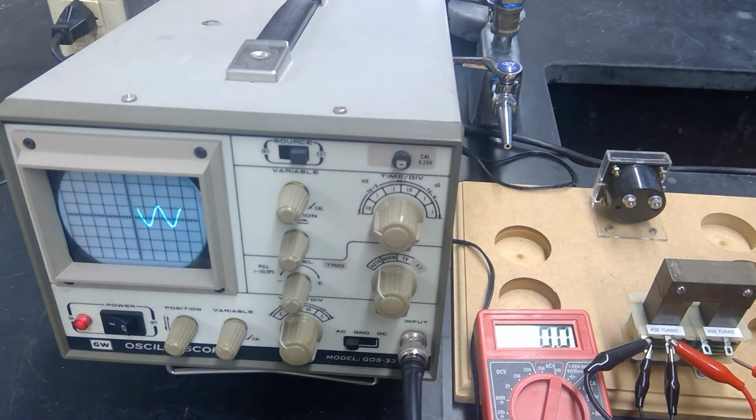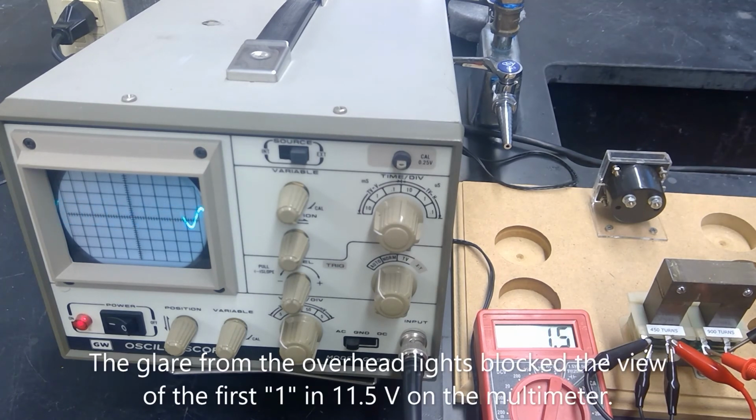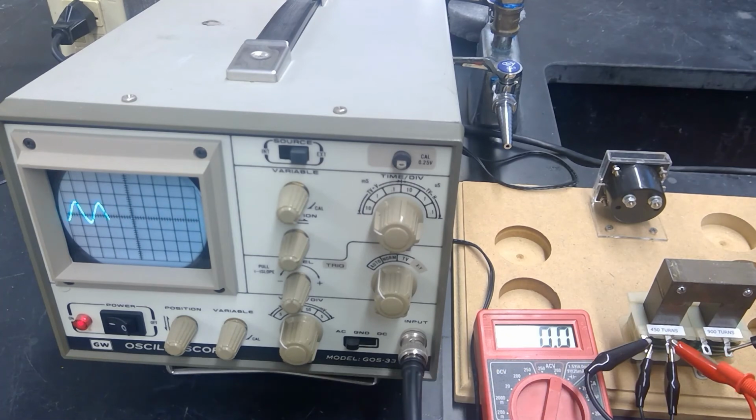But now let's take a look at the secondary. And sure enough, it's a lot bigger power. As a matter of fact, in theory, if we had a perfect transformation, because this is the double number of turns, we should have double the voltage. So 5.9 would double to about 11.8. Now we didn't get that. We know there's going to be some losses, but that's reasonably close.